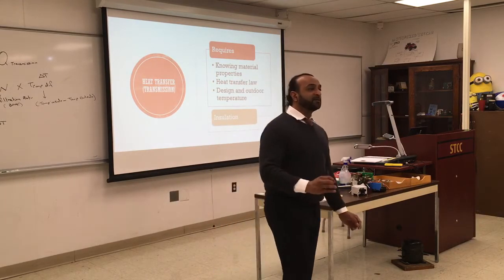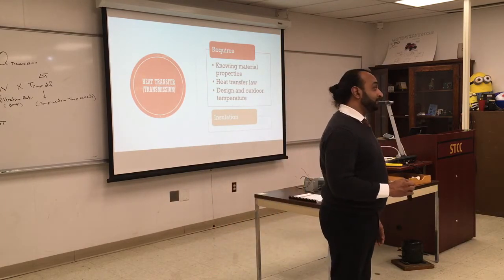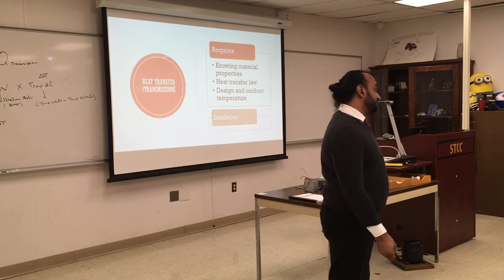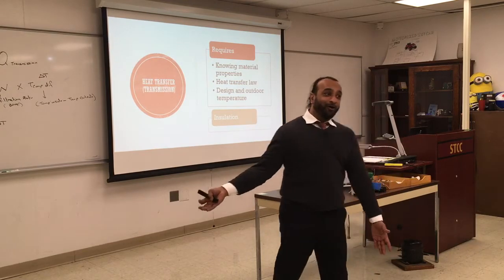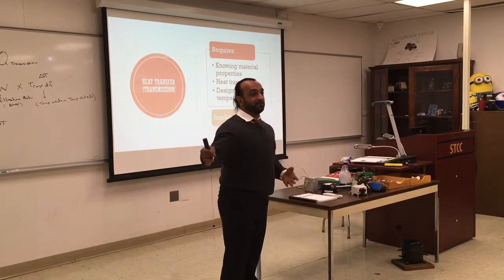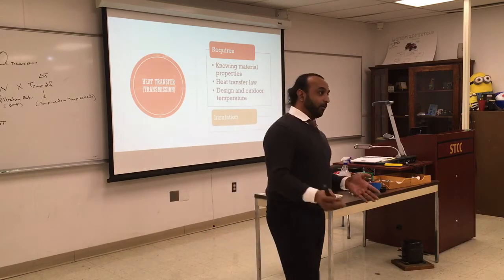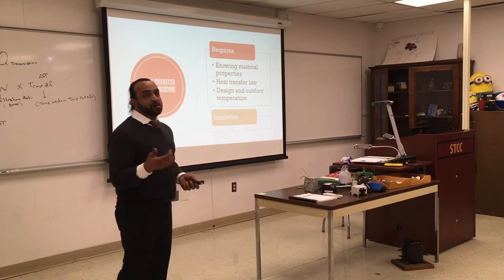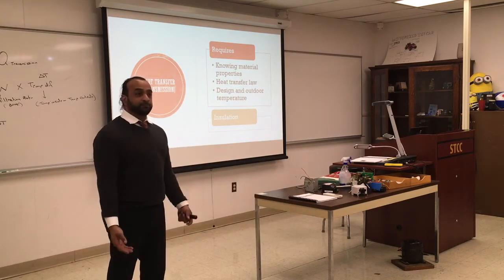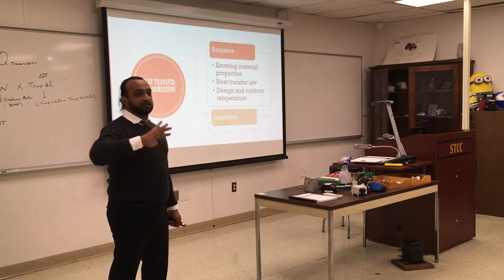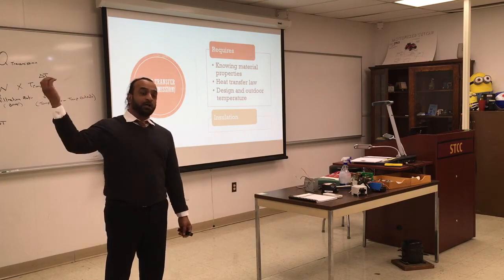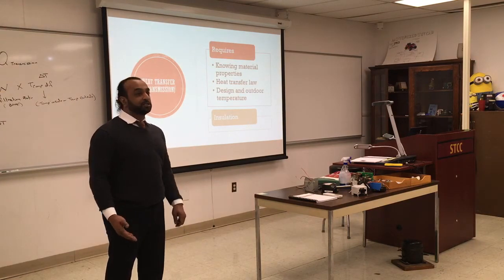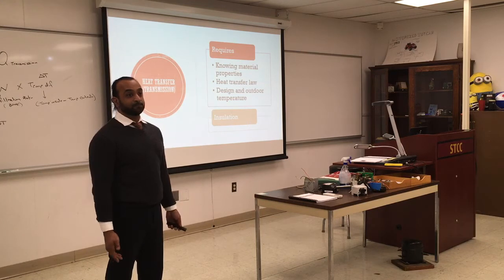And it's always better to build things well than to try to fix it later. You're going to open the wall and put some Mickey Mouse kind of insulation. It's better to have a wall built to be insulated correctly. Because if the wall is already built, what are you going to do? You have to either take the drywall off and stuff things in it, or you can make a hole and pump some loose insulation, which is not going to be that good. So it has to be packed.